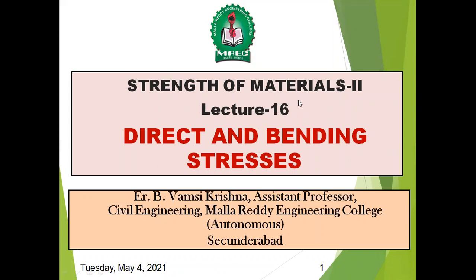Coming to bending stress, go back to your strength of materials again. In the second unit, there are topics called shear force and bending moment. In shear force and bending moment, is the load parallel to the longitudinal axis? No. There, the load is perpendicular to the longitudinal axis, right? So that's how your shear force and bending moments were calculated for a beam.